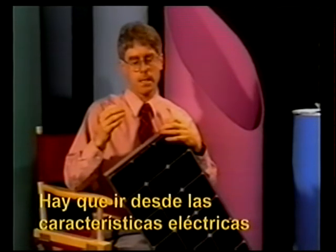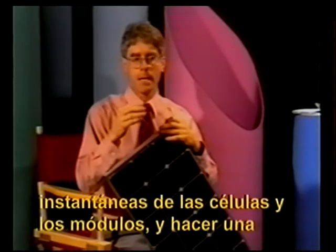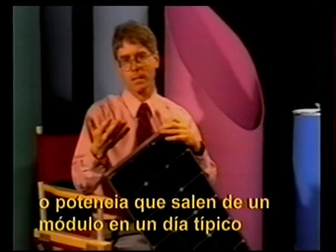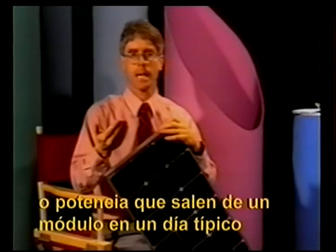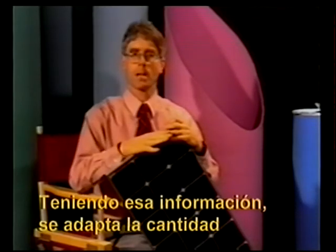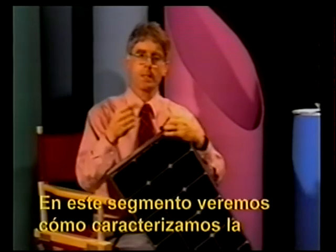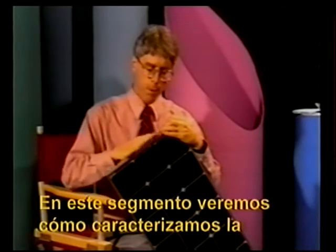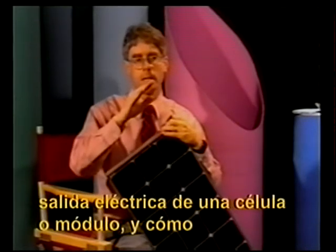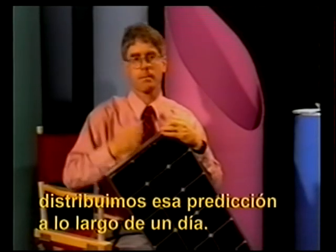We need to go from the instantaneous electrical characteristics of our cells and our modules and make a translation to be able to predict amp hours or watt hours or energy out of a module in a typical day in a particular location. With that kind of information, we can match up the number of modules to the size of the electrical load, and we'll be able to size our array. So in this segment, we're going to look at how we characterize the electrical output of a cell or a module, and how we spread that prediction over an entire day to accumulate energy out of a module.